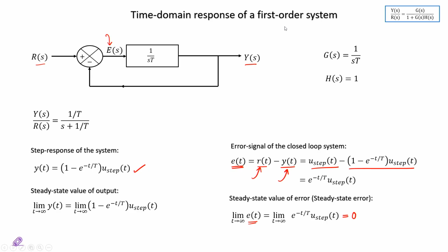Okay. So what I want to show now is that all these are fine, but the expression y(t) here depends on what? It depends on the term 1 by T, and that is very important. What was 1 by T? Minus 1 by T is the pole of the system, remember, found just by finding the roots of the denominator. So this 1 by T is a very important term.